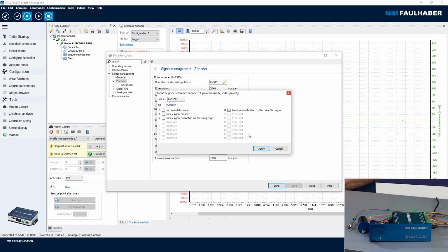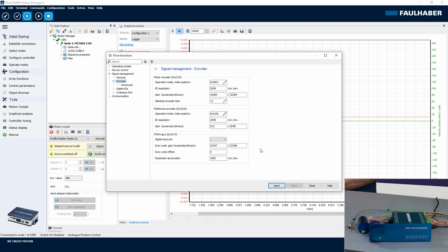So one has to be changed here, apply it, and we might have to reconsider the scaling here, because using a pulse signal, a single one only, of course there is no quadrature count, so I do get now these 512 pulses per revolution of my dial. And when, in that case, for example, I want to have a single turn of my motor out of a single turn of the dial, with these linear Hall signals, it's 4096 increments per turn of my motor.